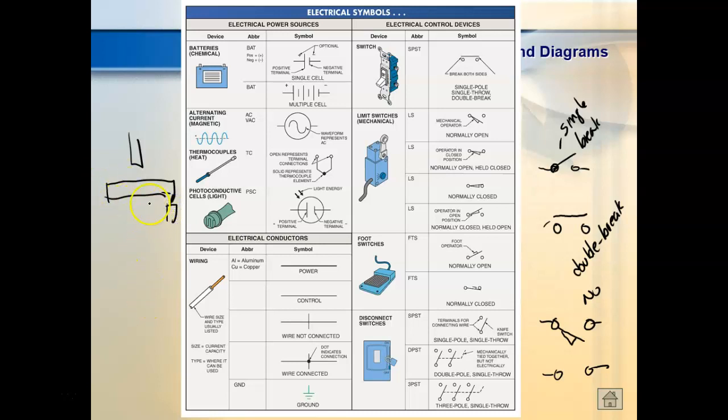So when this thing moved back and forth, let me draw it over to this side. When it came over to this side and the machine was right here, it would hit the limit switch and it would tell it to reverse, and then it would do what? Okay. And then over here it had another limit switch, and when it hit that side, it would go back and forth. We've seen them count. This one wouldn't count because it's so hard to trigger. But we'll look at some small ones. They have a whip sitting out there instead, and when something goes by, it just knocks it out of the way, and that counts things.